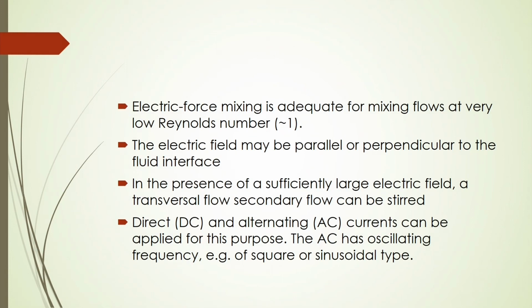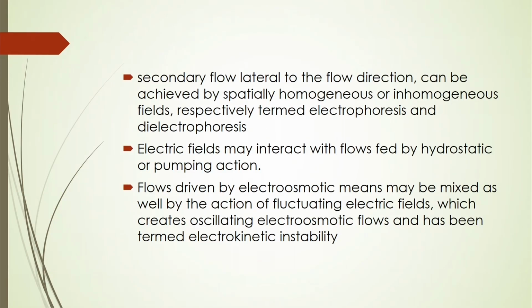Direct DC and alternating currents can be applied for this purpose, and AC has an oscillating frequency, for example square or sinusoidal. This oscillating frequency will govern and enhance the mixing process. Secondary flow lateral to the flow direction can be achieved by homogeneous or inhomogeneous fields, termed electrophoresis or dielectrophoresis respectively, and the electric field may interact with flows fed by hydrostatic or pumping action.